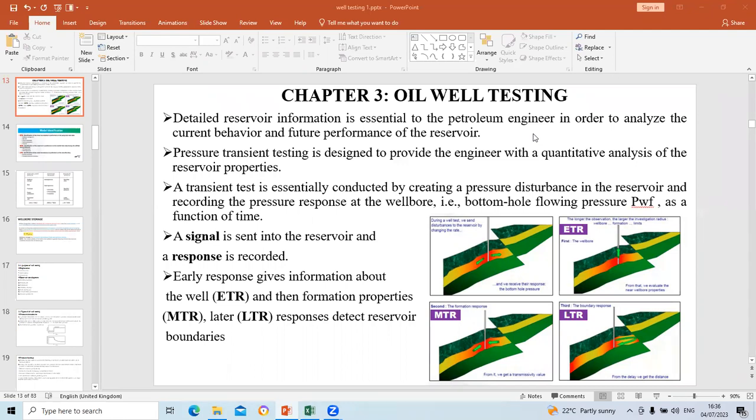So one thing we have to realize is that generally production takes place in the well. So as you're drawing fluid out of the wellbore, there is a pressure disturbance that starts from the wellbore and migrates gradually into the reservoir. And this pressure disturbance will migrate until it reaches the boundary. At that early stage of migration, that particular flow is dominated by the transient flow.